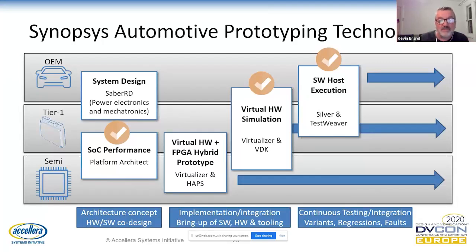With reference to AUTOSAR, for example, it replaces the hardware-dependent MCAL layers with a fast instrumented software implementation, so we're not simulating the lower hardware layers here. Of course, connectivity is still available to do things like multi-ECU, which would be bringing different pieces of application software together. It uses standards-based connectivity, things like FMI, etc.